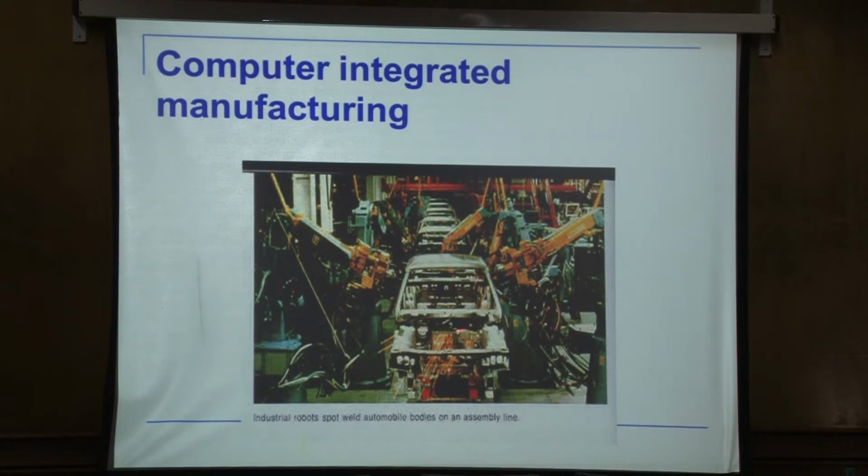how this programming is actually done in the industry is that they would have a CAD model of this. So they would initially have a CAD model of the car, a CAD model of the robots, and the full cycle time will be optimized on the CAD model first. So in simulation, they'll be optimizing the cycle times: which weld is to be done where, what is the cycle of the weld, what's the direction of the weld. And then they will come to the real world. Now, once they come to the real world, again, without the car body, they will run the robot and see whether it's working properly or not.